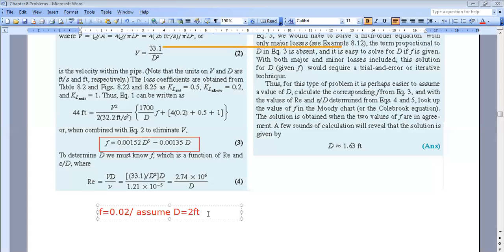But if, like previous problems, d can be easily calculated when I have f, meaning in the previous problem you don't have the second term which complicated the solution, then you can start by f equals 0.02. And if d is given and you have epsilon, then you know epsilon over d. You start by f corresponding to the flat curve, okay, as we did last time.